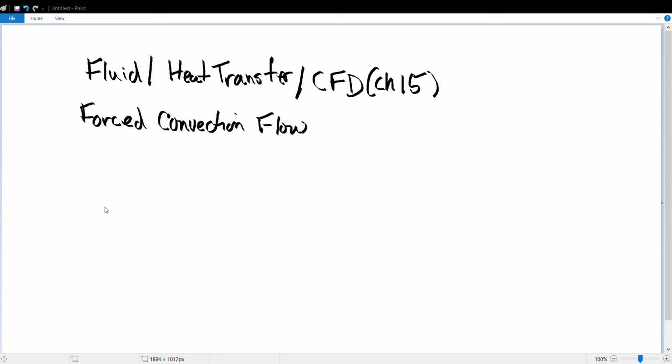And for that, I'm going to go back to where we started initially, and that's the heat transfer coefficient. Once I write this down, you'll probably be more familiar with this. We have the equation for forced convection, or convection in general. The heat rate is equal to the heat transfer coefficient times the surface area times the temperature of the surface minus the temperature of the fluid.